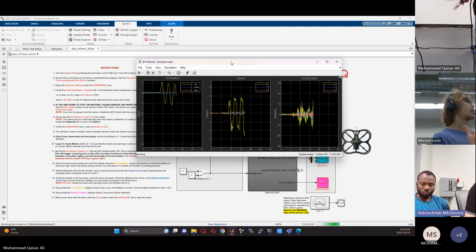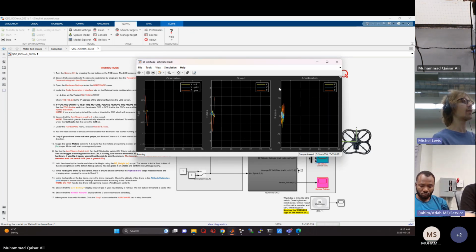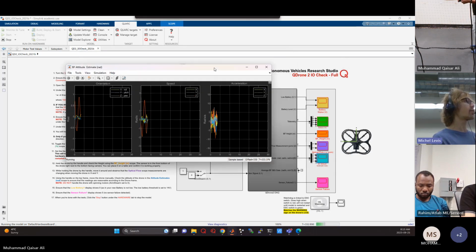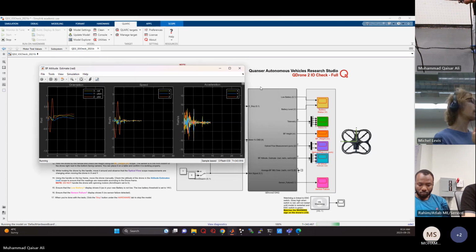Yeah, it's working. So this is an estimator on there, and the estimator is used in all the flight controllers, right? So it's basically using both IMUs to estimate its pose, but then it's also using the OptiTrack camera, the direct measurement. So it's using all three things to get the most accurate. Now, in this example, we're not, of course, using any localization yet, but it's still doing some estimation on its own. Fine. So this confirms that the IMU sensors are working.